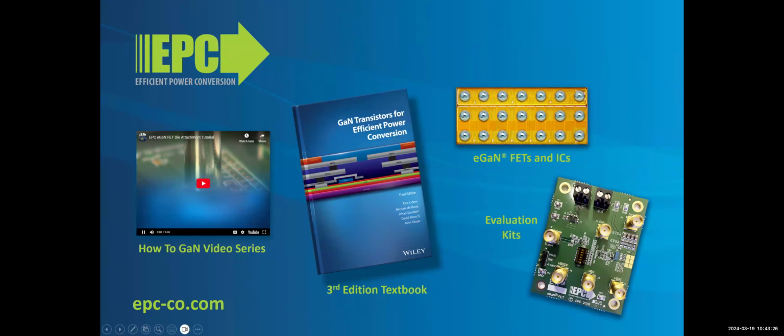Marco, our first question is: motors need below 500 volts per microsecond. GaN is much faster. Required damping loss energy of LC, delta V over delta T filters make them useful only up to less than 2 kilohertz PWM. What would be your solution for a GaN inverter with greater than 60 kilohertz PWM for reliable motor isolation?